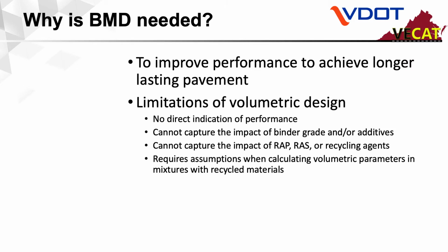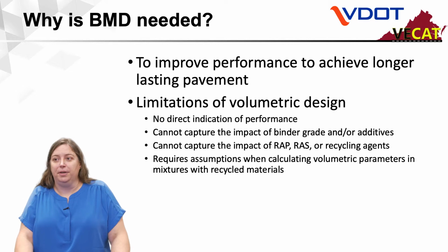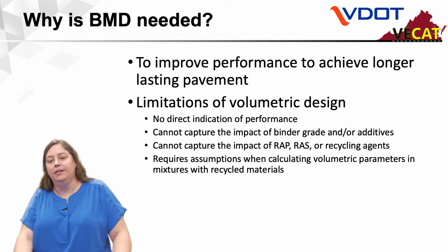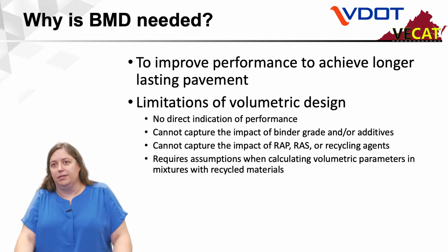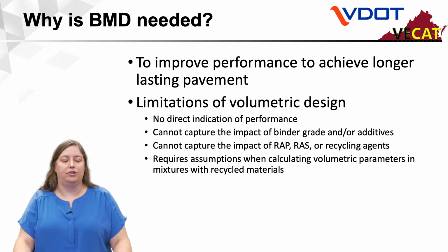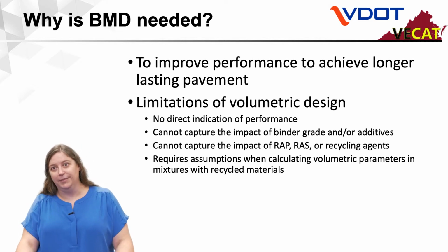So why do we need to look at BMD? We want to improve the performance of our mixes so that we can achieve longer lasting pavement. Currently, we design using volumetric methods such as SuperPave, and even before that with Marshall mix design. The problem with these is that volumetric properties do not give us a direct indication of performance in the field.